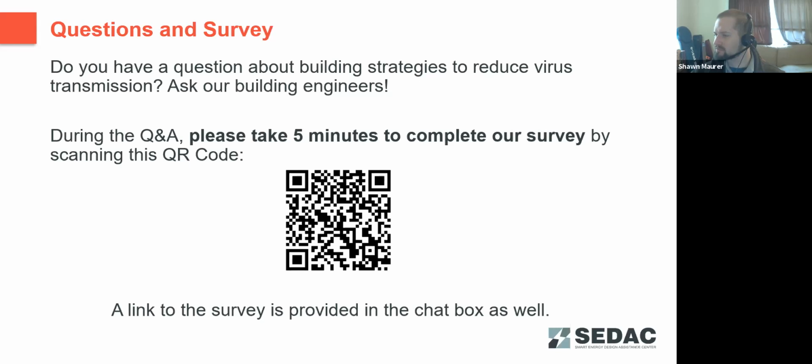We did have a comment from someone. They had an HVAC system where they tried to increase from MERV 8 to MERV 13, but had issues and had to go back to MERV 8. Their units were shutting down on limit switches, turning off the fans. So for that facility, another good option, as we mentioned, is setting up MERV 13 filters in the rooms, either with an air purifier system or setting up a box fan with the air filtration unit on it.